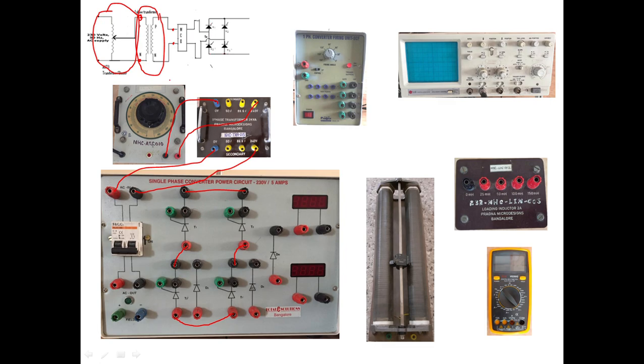And now how to connect this MCB? This MCB should be connected to either the anode of T2 dash or the cathode of T1 dash. So we'll connect it to the cathode of T1 dash. This will be connected to the MCB here. Now the other point of the MCB, that is negative, is connected to the cathode of T2. The cathode of T2 is here, so this wire will be connected here. So we have finished giving the supply to the bridge.